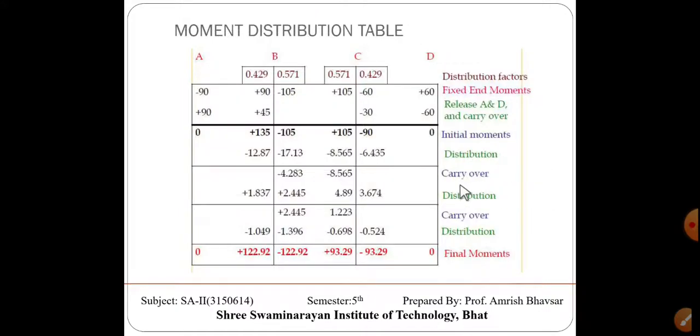Now what we are going to do? We will take the distribution table for understanding how we will get this distribution. So our joints are A, B, C and D. We will put them over here and take one reference line from that. At A our distribution factor is 1. Here our distribution factor is again 1. But B to A is 0.43. Here I have taken the precision at the third level, 0.571. At C, C to B is 0.571 and C to D is 0.429.